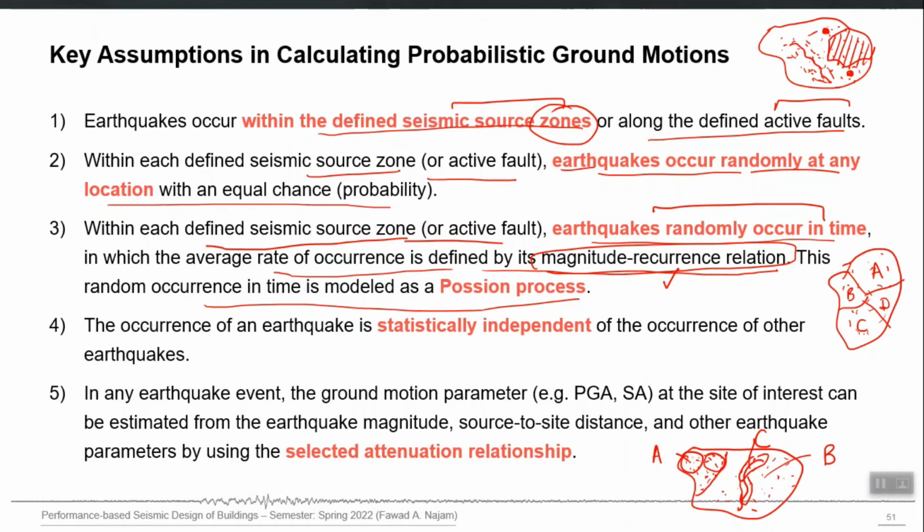So aftershocks are dependent on the main shock, right? We do not consider dependent events in future forecast. So all the aftershocks and foreshocks should be removed from the historical data, and the data used for future forecast should only contain main shocks, and main shocks are assumed to occur randomly in history, right? They are independent events.